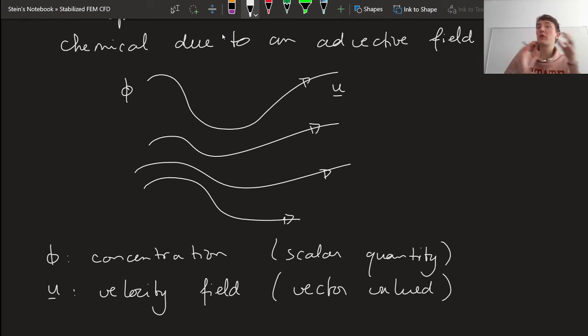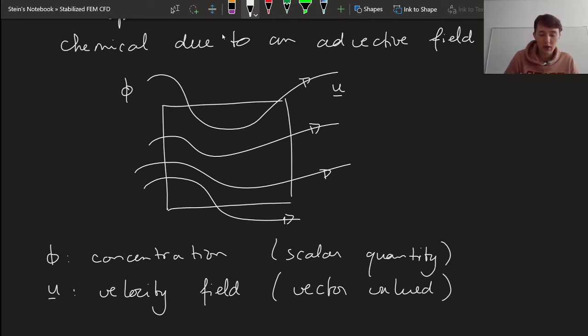And for the Eulerian perspective, we have to look at control volumes, and we're trying to find a balance of something that flows in of that control volume and flows out, and there's a balance between those. So the balance law that we might set up for this advection-diffusion, we first have to define a control volume. So let me draw some arbitrary shape here. That's going to be my control volume. This has a normal vector on each side.